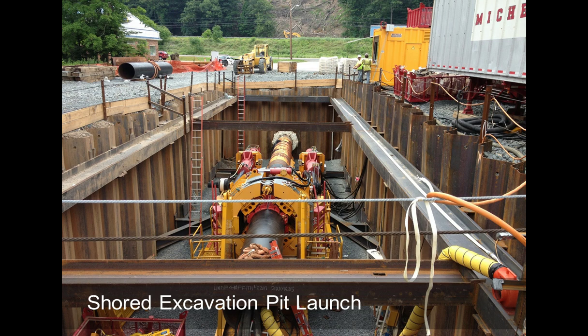This is an example of a four-sided pit launch. We had to get a little deeper here to get under the interstate that's in the background of this picture. The track hoe that you can see in the distance is actually excavating the exit pit. So this was a relatively short crossing, and we had to get pretty deep pretty quickly to get under that interstate. We didn't have a lot of room behind us in this case because the valley of the Delaware River was just behind the photographer here.